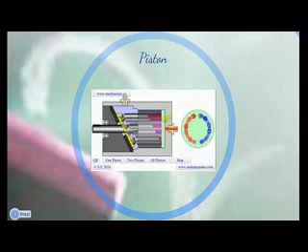Springs in the cylinder barrel, which are not shown in this animation, force the pistons towards the swash plate. Let's observe the motion of one piston inside the cylinder barrel. Notice that during one revolution, the piston moves inside the cylinder barrel from the top left to the bottom right, and back to the starting point.